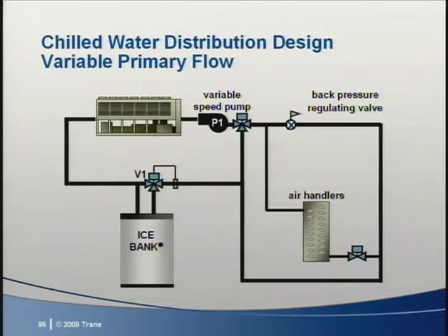Other potential issues are that IcePick does not model variable flow, but we believe the selections are probably conservative. Controls get more complicated as there are now more flow limits to manage for the different control modes. And finally, night cooling is more difficult because there is no longer a natural way to blend the water sent to the coils during charging mode. So condensation on piping, valves, and fittings must be addressed.